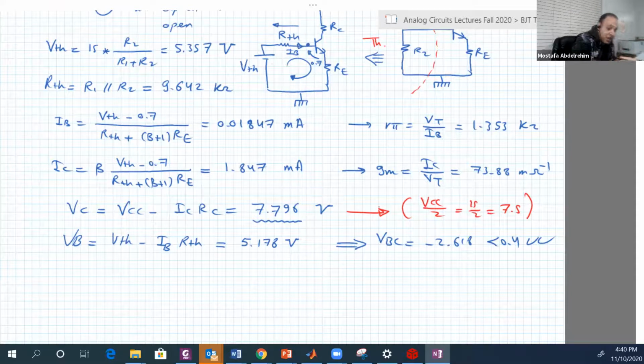Good. That's all for the DC analysis. We get GM, we get RBI. We check that we are really working in the active region. That's all. Now we go to the AC analysis.